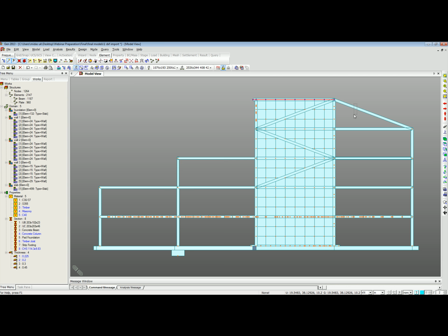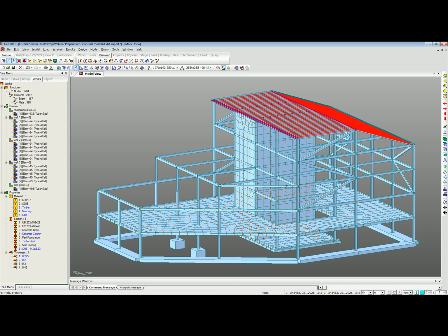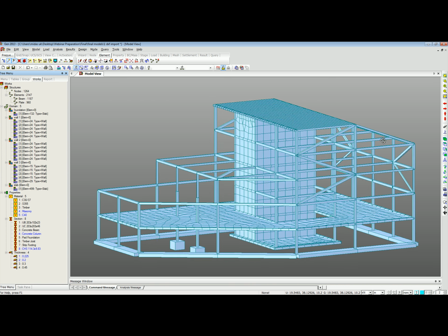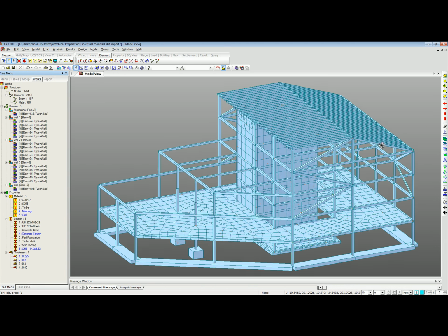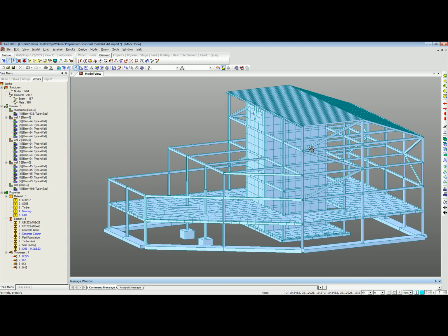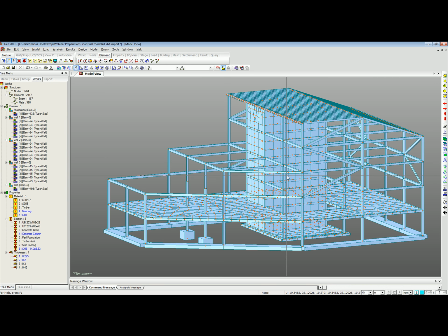The timber roof, again select the areas you want to. You can see it's quickly defined all of them and located them. Again, I'm just going to drag and drop some predefined details. There is a complete database on these, but if you have got something irregular or unusual, you can define your own sections in midas Gen. Let me put these last couple of slabs on, and that should be our model ready to go.